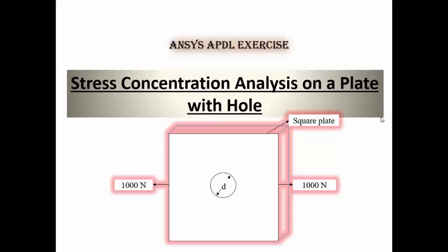So we all know that stress will get concentrated at any specific portion of a structural member under loading condition if it has non-uniform stress distribution due to some irregularities in the geometry of the structural member. Okay, so it is measured by the parameter stress concentration factor. Stress concentration factor is denoted by the letter K, and it is the ratio between maximum stress and nominal stress.